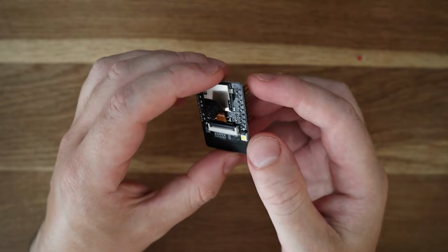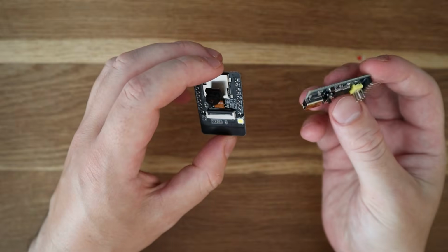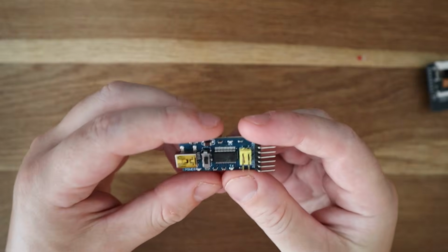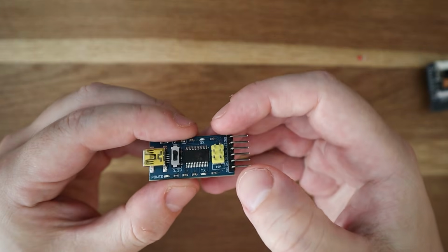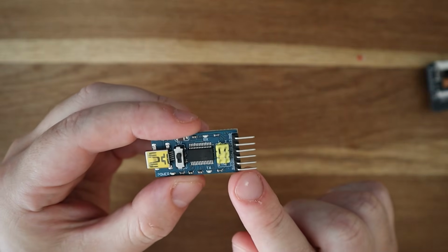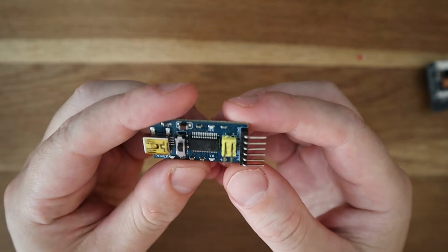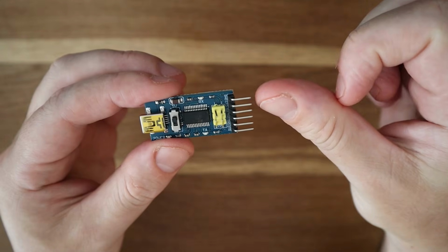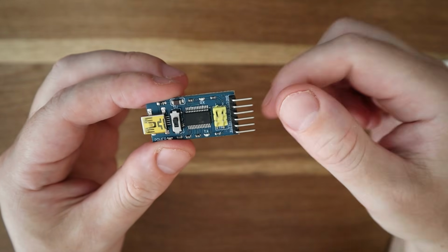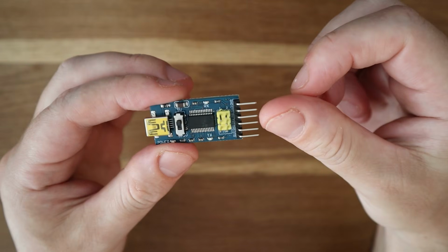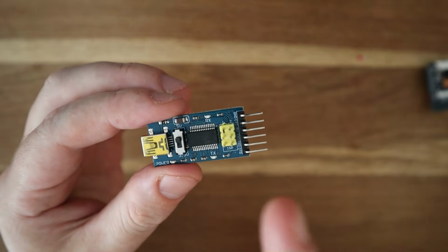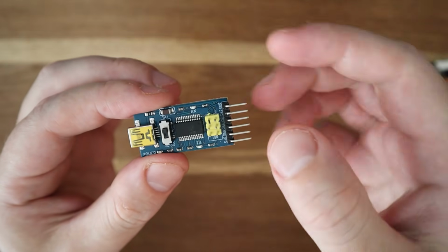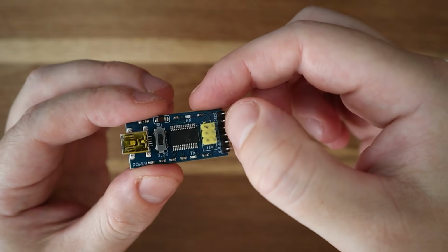And now let me show you how to do all the wiring with the FTDI connector. Something that's very important regarding the connector is that all these pins over here may be located in a different position than the one I show you in the PDF file, right? If I take a look at the names, the first one starting over here is ground, then the third one is 5 volts, and then these two pins over here are the ones we are going to use for the data transmission. So please pay attention to your specific FTDI connector and take a look at the names of each one of the pins that you're going to see here, right?